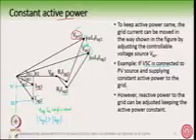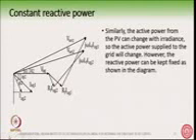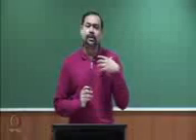So in a similar way, I can also draw a phasor diagram in which we are able to exchange a constant reactive power, but the active power will change, and the phasor diagram is shown here.